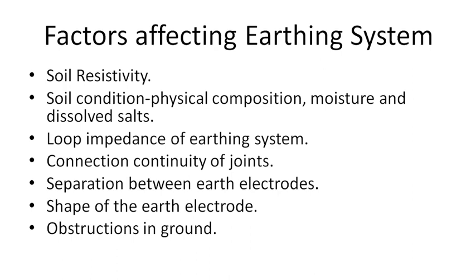Then it also depends on the loop impedance of the earthing system. That is, it is not enough that we earth our system; the conductors which we are using to connect to the earth should have the minimum loop impedance, then only it will take the shortest route possible. Then the connection continuity of the joints.